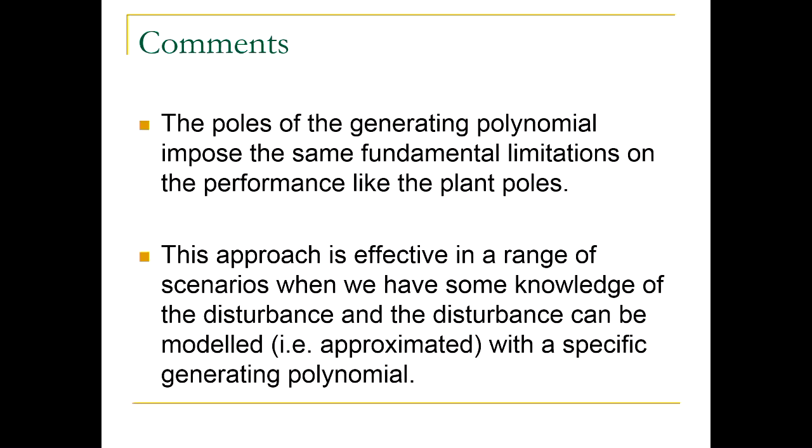You can then generate them with these polynomials and reject approximately any sort of disturbance in this way. We are talking here about exact rejection. We will learn later on, when we talk about frequency domain methods, how to attenuate, but not reject, disturbances that belong to infinitely many different frequencies, frequencies in an interval. That's a much more powerful but different method, because these internal model principle controllers exactly reject disturbance.